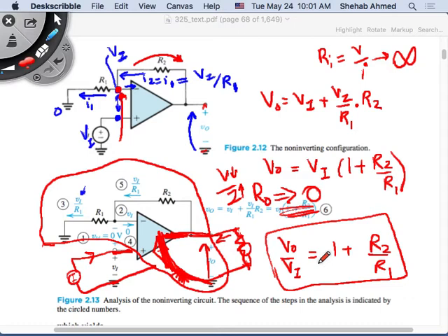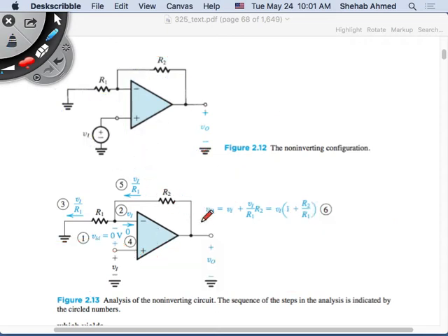And we will see how else can you derive it. We derived the equations already, so you can also easily derive the output equation using a voltage divider. If this is an input voltage, this input voltage is placed across this resistor, in series with this resistor to ground. This node here has a voltage of VI.